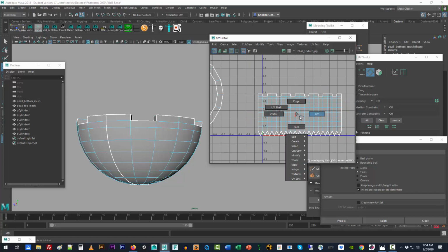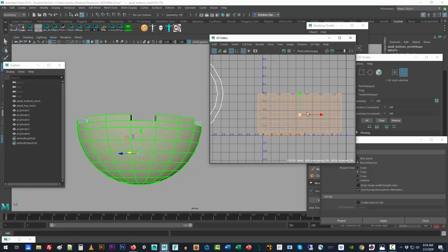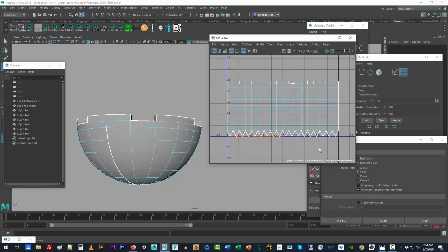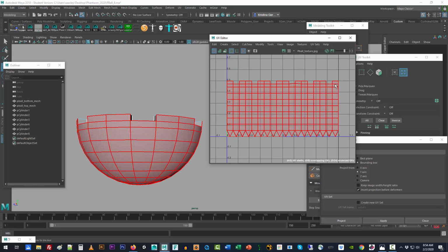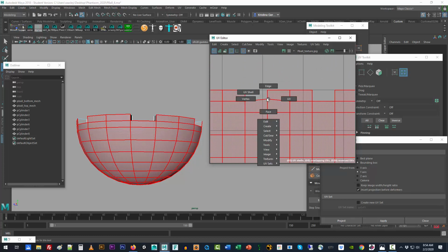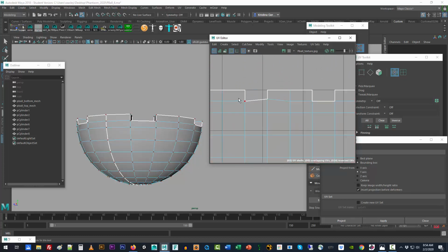Let's grab the UV shell again and just move it over a little bit so we can have all of it on the surgery table. And this is okay to eyeball because you're going to be moving this around later. And this allows us the chance to jump in and start cutting this up. Now, one of the things that we're going to be doing is not just cutting UVs, moving UVs, but also snapping UVs. And since the grid snap in here does not necessarily align to where we have the lines, there is something we can use to fix little mistakes like this,